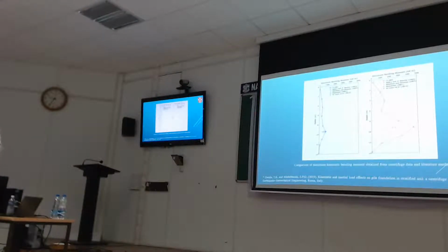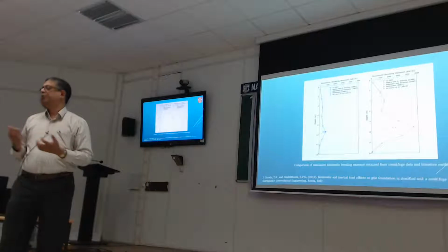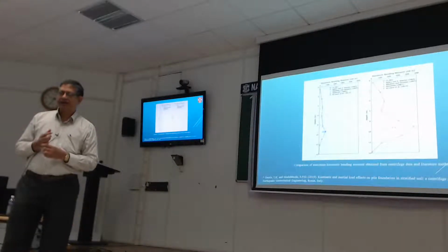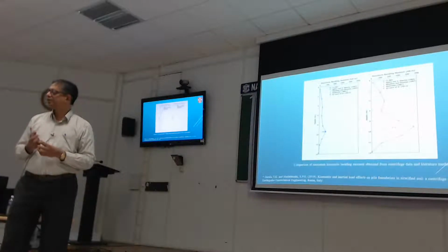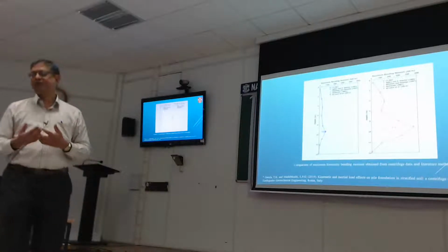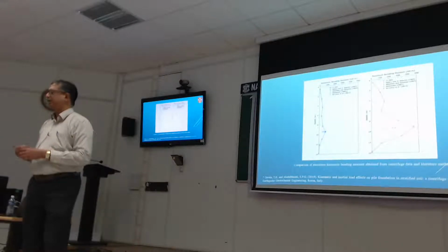And I briefly mentioned that although we made these calculations using the authors' equations, we were using, as we are supposed to, and as you would if you're a consulting company, the shear modulus of the soil at small strain, because that's all you will know. You don't know what happens to the stiffness of the soil under a particular earthquake.